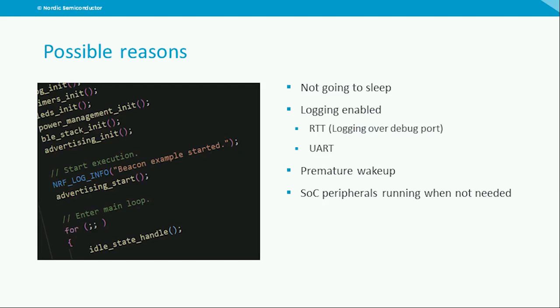Forgetting to go to sleep will cause the infinite loop to be processed and the CPU is spinning as fast as it can, doing nothing at all. That is why just checking that your device is giving you the functionality you expect it to is not enough. You also need to verify it does as expected when not doing anything at all as well.